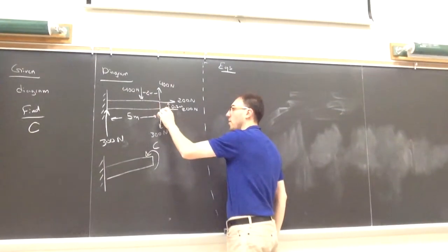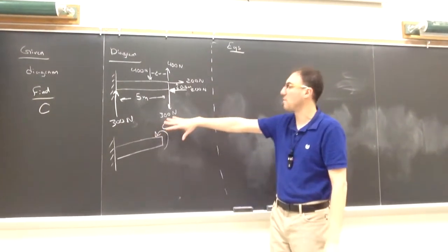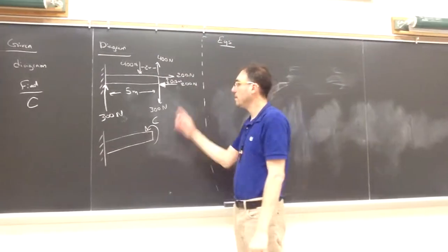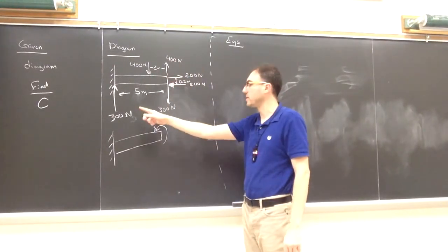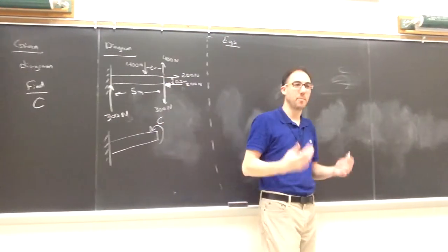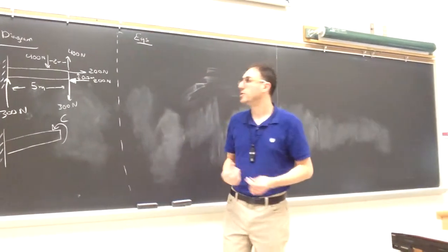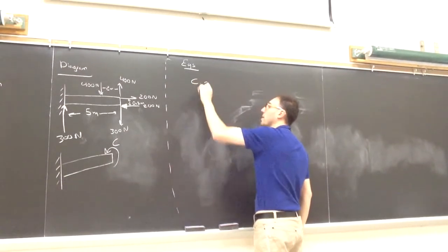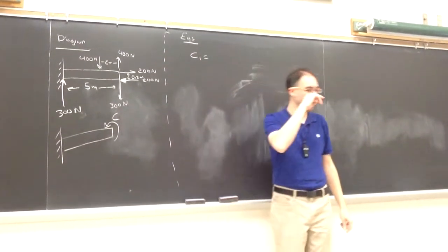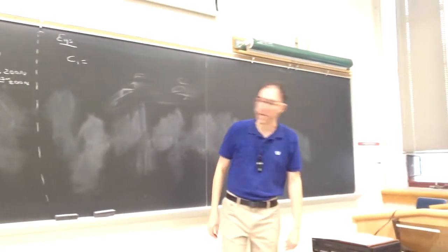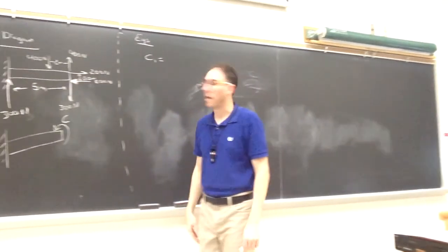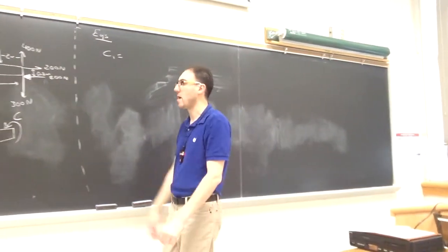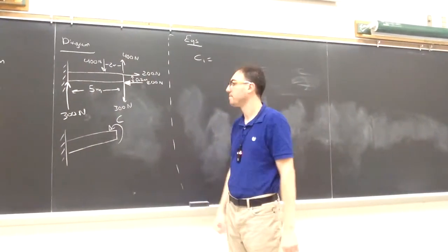And this is only the case that we'll be able to simplify it this far because every force is paired with an equal and opposite one. So one pair at a time, we can start to simplify and see what's the couple or the moment contribution due to that particular pair of forces. So I'm going to start with just what I'll call C1 here, which is going to be the moment or the couple caused by the 300 Newton pair. The order I start in doesn't really matter.